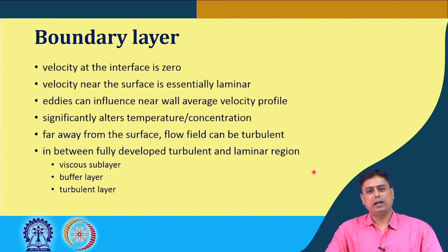But sometimes, although the fluid happens to be laminar in that layer, eddies can form, due to turbulence or some obstruction or some influence of the geometry, that create some eddies or wake. That alters the flow profile in that layer of the laminar flow, and it influences the near wall average velocity profile. But it hardly changes the overall profile at the bulk velocity.